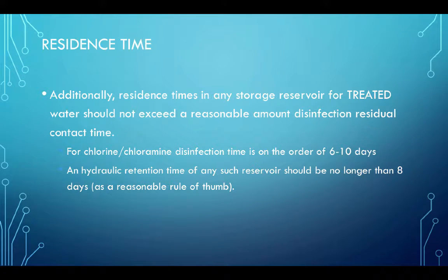Additionally, we want to consider residence times. For treated water, we want the residence time not to exceed a reasonable amount of time so that the disinfection residual contact time is maintained. For instance, for chlorine or chloramine disinfection, a residence time of 6 to 10 days. The water would still be treated upon leaving such a reservoir.